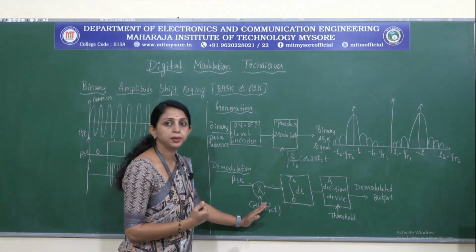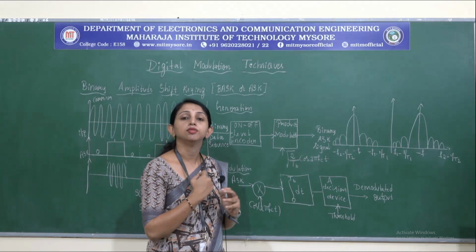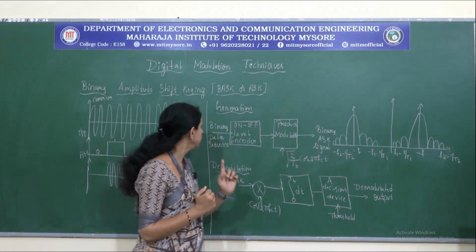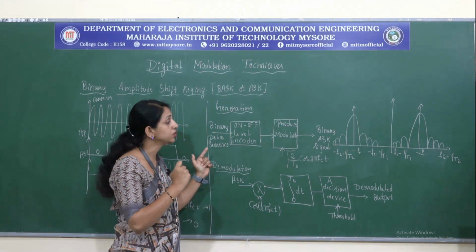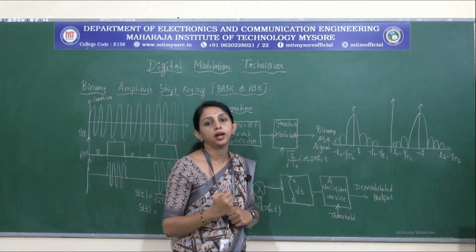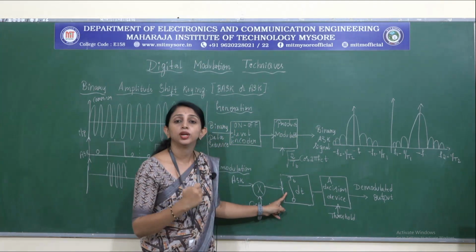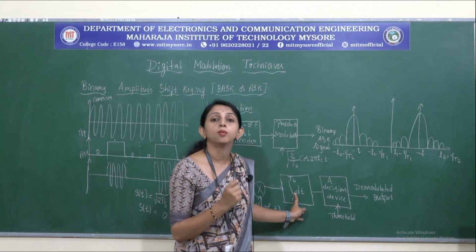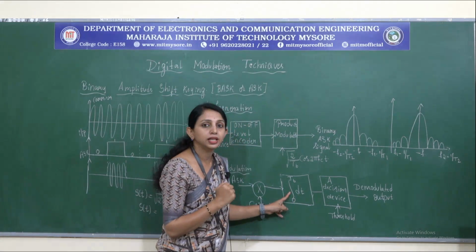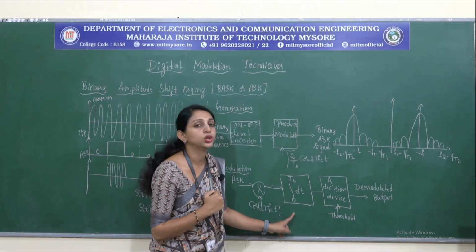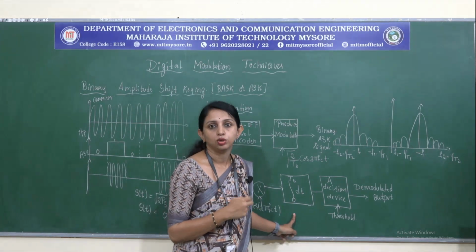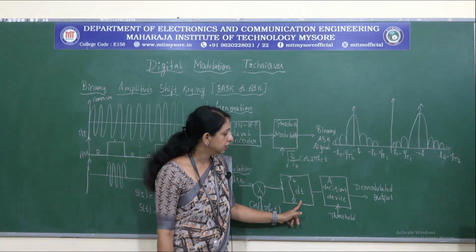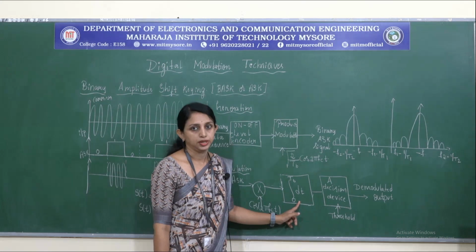From this multiplication, the data we are going to get will be continuous, but in the output what we require is a binary data sequence which switches its values between 0 and 1. Hence here we need to integrate the continuous pulses in order to get the sequence in the form of pulses. Along with the integration of successive values, we are going to do the low pass filtering operation also, that smooths out the values. That is, LPF will also be done here along with the integration operation.